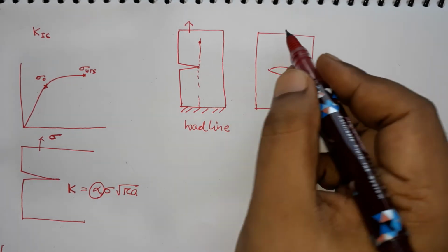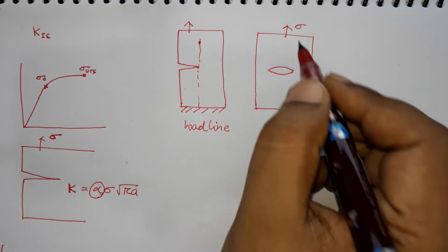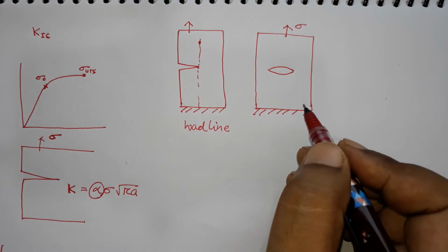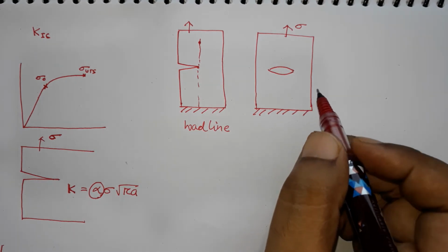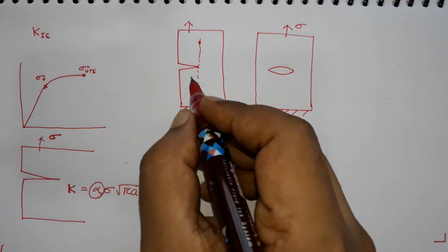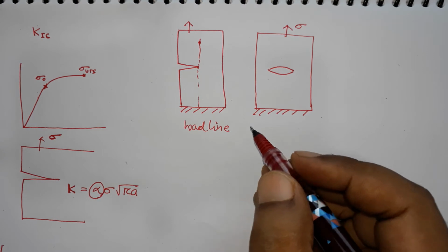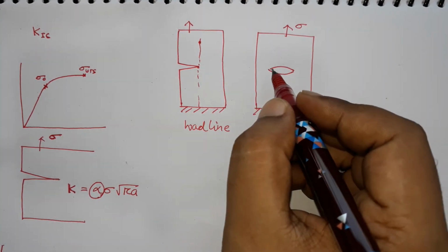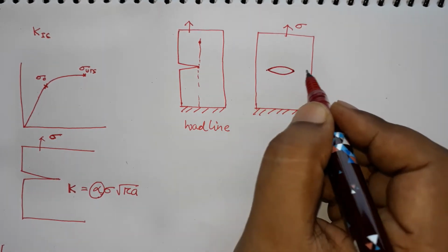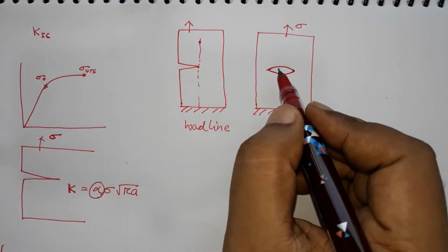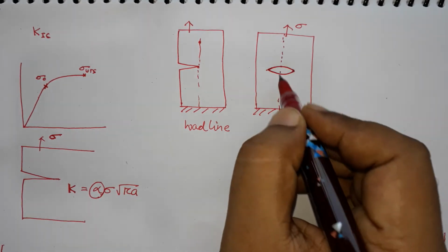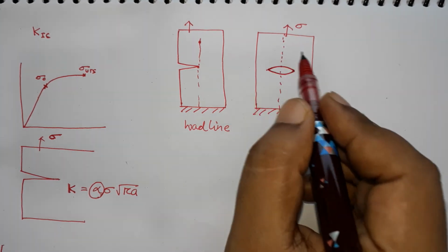Okay. So, in this case also you apply stress and you fix the lower end, but given the same material, if you apply the stress, then you will get different amount of stress intensity factor even if the crack lengths are same. That will be because of the constraint, and this constraint is a little different from what we addressed before. So, you see, if you divide it hypothetically, then the left part is the mirror image of right part.